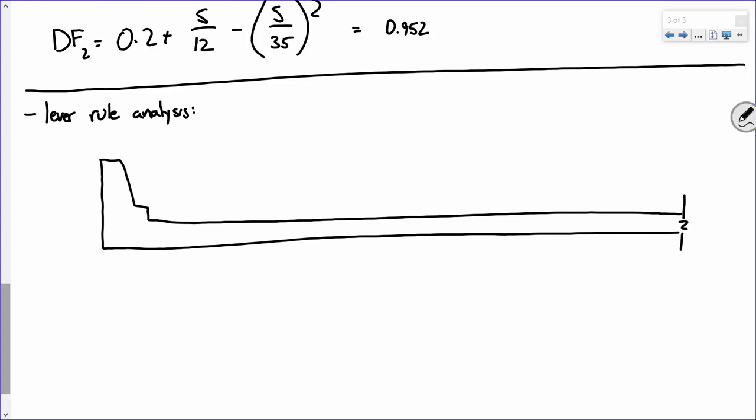Okay, let's put some dimensions on here. Does anybody know that dimension right there? I like to keep that in inches. What is this dimension? 3'6". Okay, that's the total overhang. I'm talking about just the barrier width. 1'6". That's the barrier width, so that's 18 inches. Make sense? That dimension is going to be important here in a second.